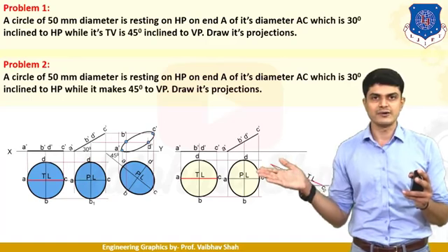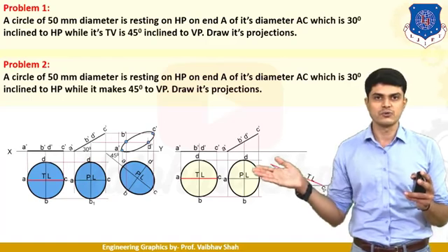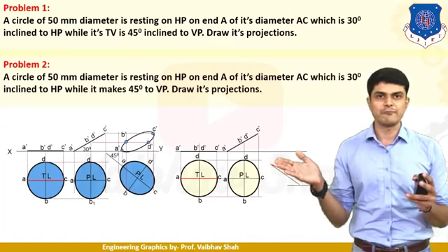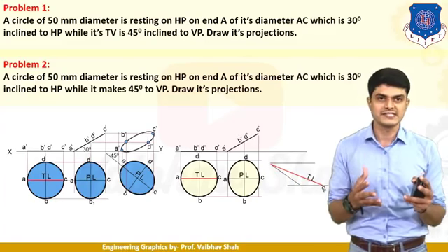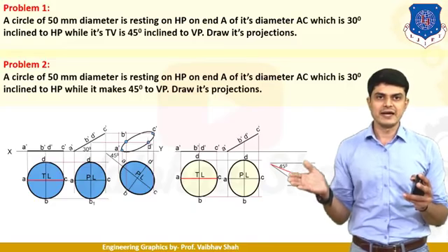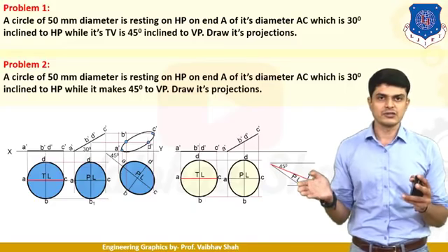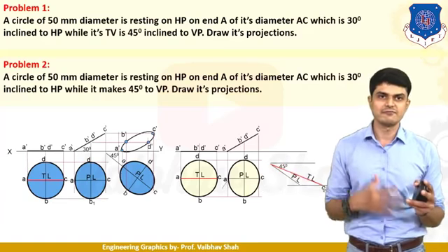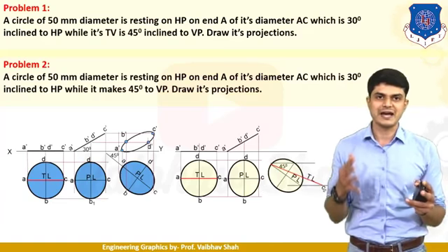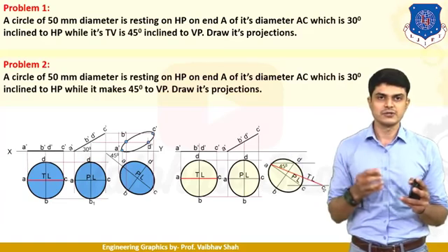So we should now take the dimension of AC onto your rounder, put a point at point A and try to cut this locus line in order to get this point C. After that we will be having plan length drawn. And then on this plan length, we should simply redraw this figure, and we'll be having this circle drawn into this plan length. So this is nothing but your circle.